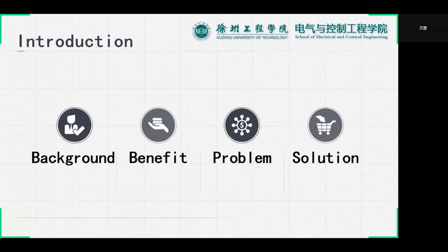As an outstanding representative of the third generation of wide bandgap semiconductor devices, Cascode Gallium Nitride HEMT, which stands for High Electron Mobility Transistor, utilizes a cascode structure to achieve the normally off nature of GaN devices with unmatched steady states and dynamic performance of silicon-based devices.